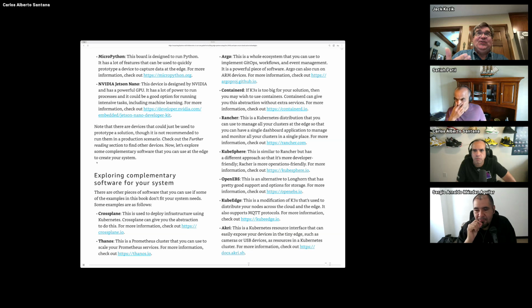Yes. And so you tell the device, we're only going to talk to you once a day. So all you have to do is turn on your receiver once a day, and if you hear anything, then turn on your transmitter and respond. Otherwise, you're just off. And so it's very, very low power. Your mobile phones are always on and always sucking battery. These IoT devices just can't work that way. You can't afford to change the batteries every year.